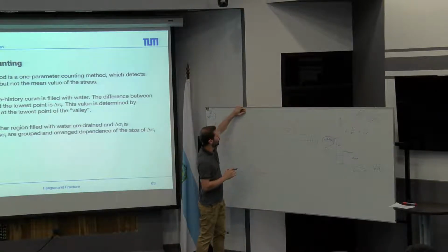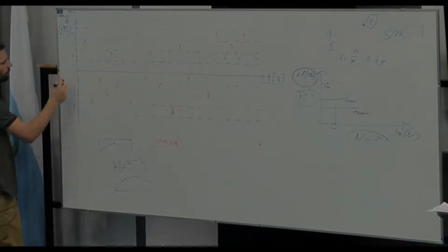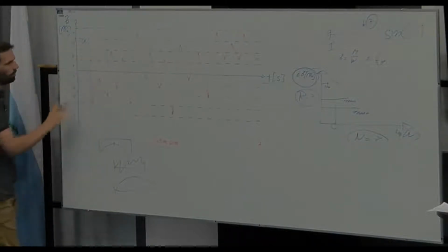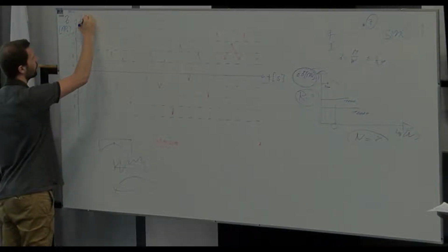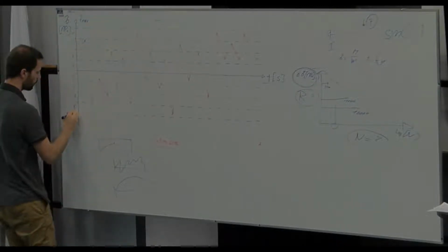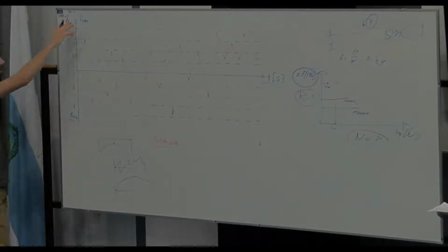What they are doing is, at first, that they have to apply a classification procedure, and this classification procedure is shown here at first. You have the stress range, which goes from sigma max to sigma min. This interval you have to divide into, usually, 8, 64, or 128 different classes.